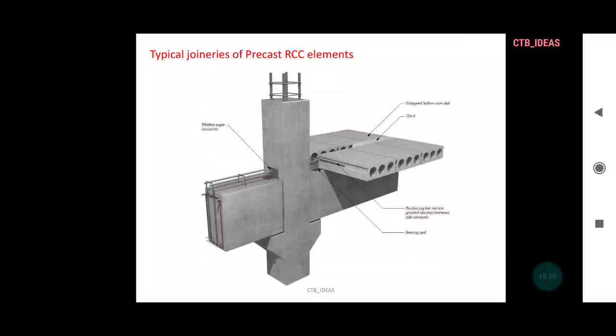And now how to secure the slab on this particular beam? You can see the slabs are placed on either side, and then there are steel bars through the grout keys, and the slab is resting on the bearing pads which are already there on the beam. Having secured the reinforcement, you have to pour cement grout in the gaps to fill and tighten that particular joint.